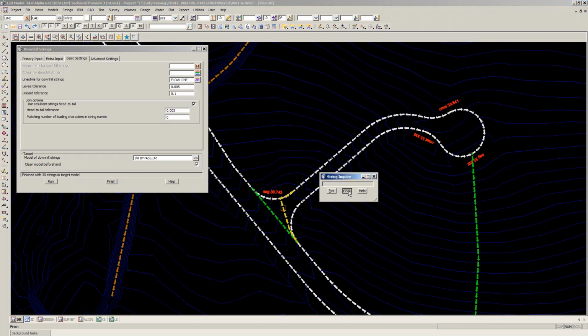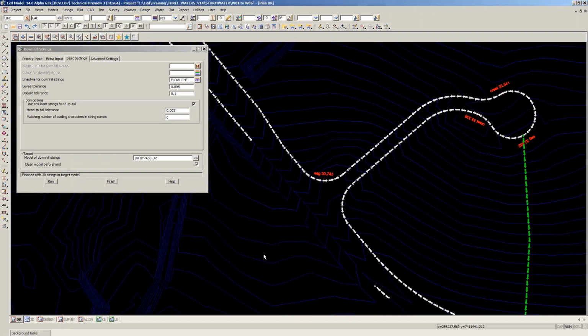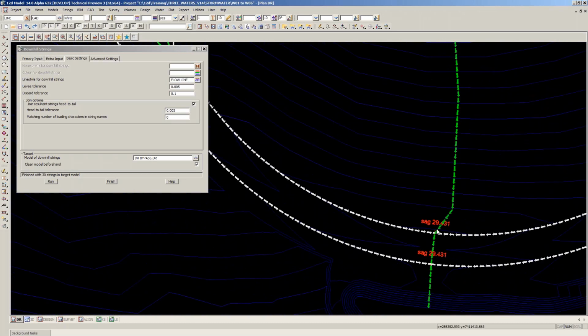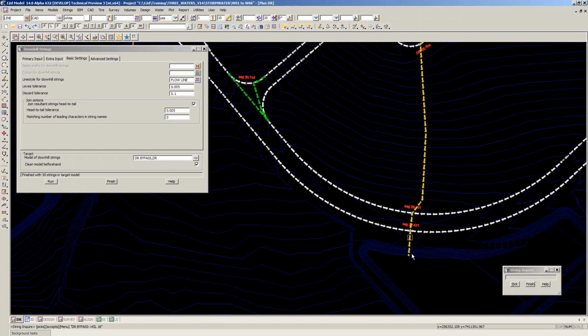And all I mean by that is I'll do a quick example here. I'll just work on, say, this one. Down here at the sag pit, I don't need to do anything. That's all working nicely. But again, this string is not only conveying the flow coming down the easement, but it is also conveying the sag pit here. Once it bypasses, it's going to spill over to the other sag pit, and this sag pit will spill into the basin. There's a nice cascading arrangement there. So that one's already done.